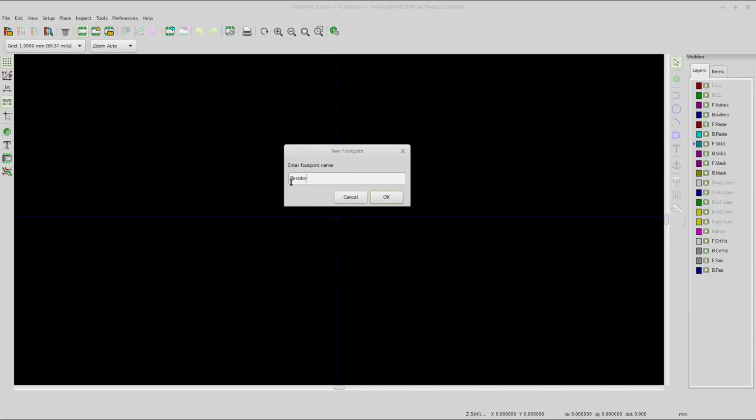So we'll go ahead and call it resistor, but I think we need to have the length in here at least. You could give it length and width if you like. So you could call it 6 millimeter, but you might want to call it L 6 millimeter or 6 millimeter L or something that denotes that that's the length, unless you've got a real common naming scheme that you're going with. Maybe throw in an underscore there as well. And then after that, no spaces, by the way.